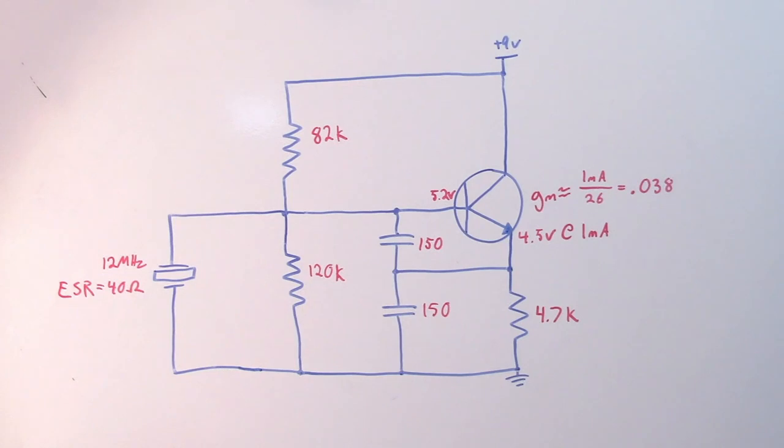It's not that accurate, but it is kind of a worst case scenario, and any calculation we do of the internal RE here, unless we actually sit down and measure it with test equipment, is going to be an approximation and an assumption anyway. So I usually, just for simplicity, use the maximum ESR in place of my RE and plug that into my equations.